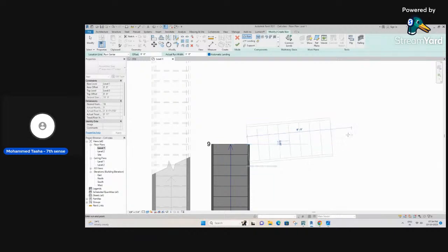Now, if I want to change that, I'll go to the location line on the top, in which we have exterior support left, exterior run right, and run left. You have 2 options over here. You can select any of these. I'll select run right. Now you can see the staircase is going towards the right direction, and it is created exactly to the left side of that point.